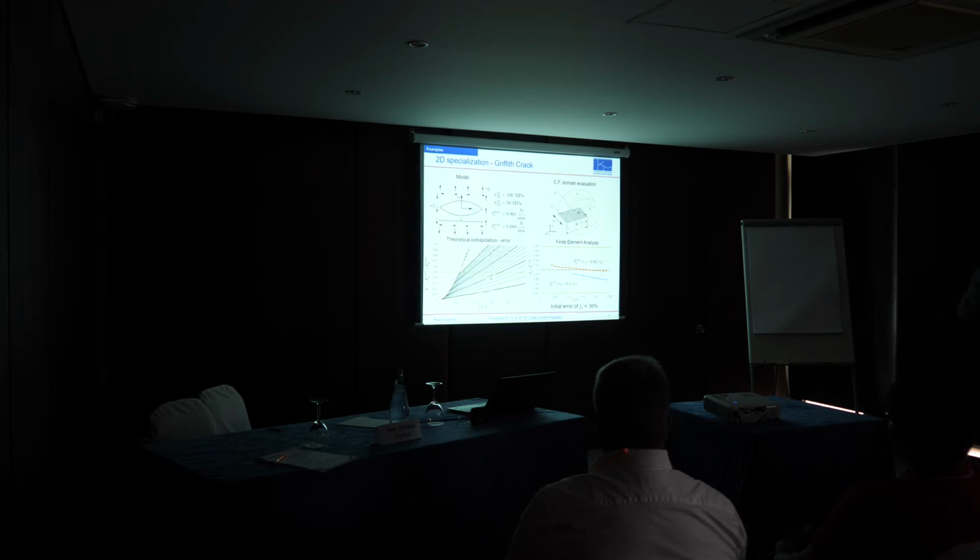This is the calculation of J2 for this problem under mixed mode loading without calculating crack face integrals. We see that depending on our parameters, R1 and R2, which are portions of the crack face that we take into account when calculating our forces, the results are not very sensitive to the choice of these parameters. It is not difficult to compute quite good results with this method without doing any complex calculations.